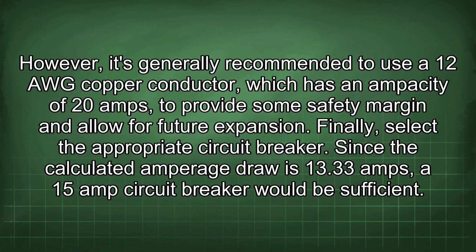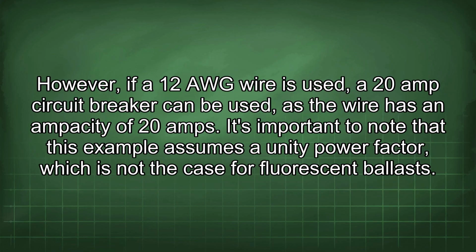Finally, select the appropriate circuit breaker. Since the calculated amperage draw is 13.33 amps, a 15 amp circuit breaker would be sufficient. However, if a 12 AWG wire is used, a 20 amp circuit breaker can be used, as the wire has an ampacity of 20 amps.